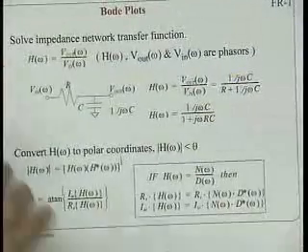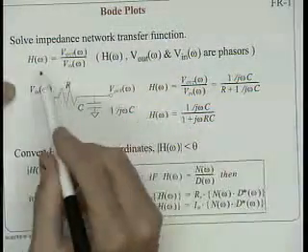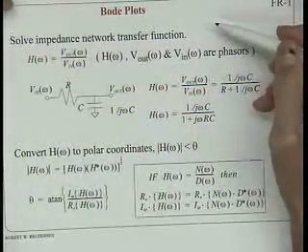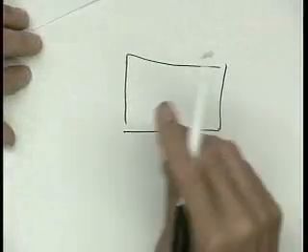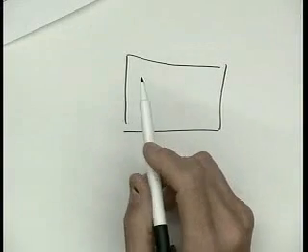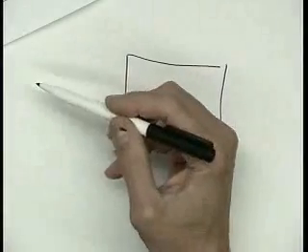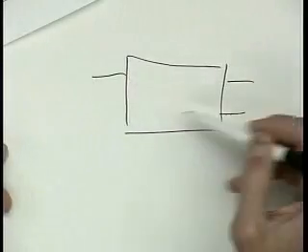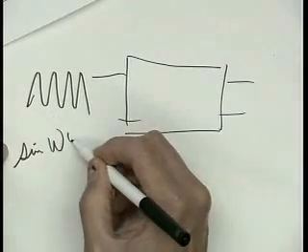Okay, quick review of how we analyze frequency response. What we will do is use something called Bode plots. Okay, hopefully you've seen this before. What we're going to do now is change our point of view. Before, we thought of our circuits as being small signal variations at basically very, very low frequencies, okay? We assume the frequency is nearly 0. We are now going to think about what's driving our circuits, our 2 ports, as being a sine wave characterized by a frequency omega. So it's sine of omega t.